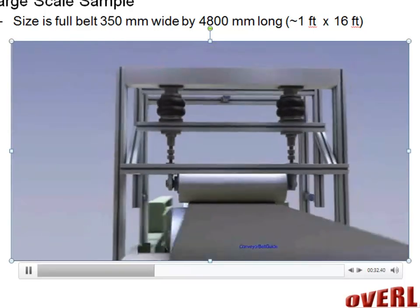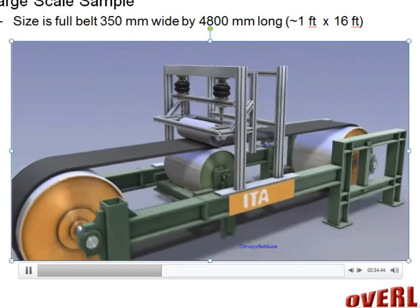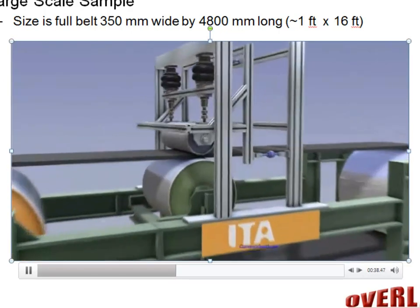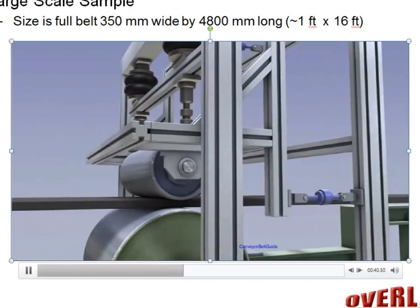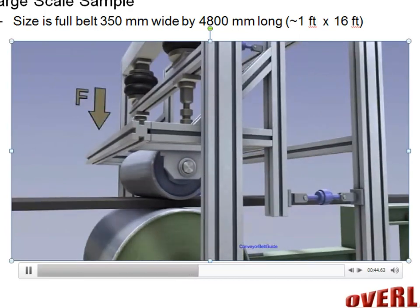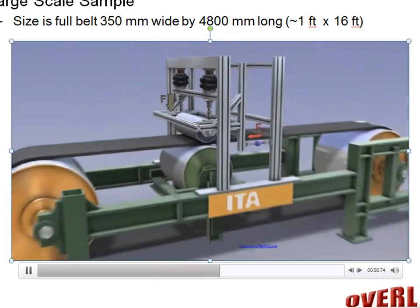You can see in this video here, we're really seeing an example of what this test machine is testing. A belt 1 foot wide, going around two pulleys at whatever speed we want it to. The top roller exerts a pressure on the belt, simulates what the load is on the belt, and we measure the resistance on a load cell there, representing F sub E.